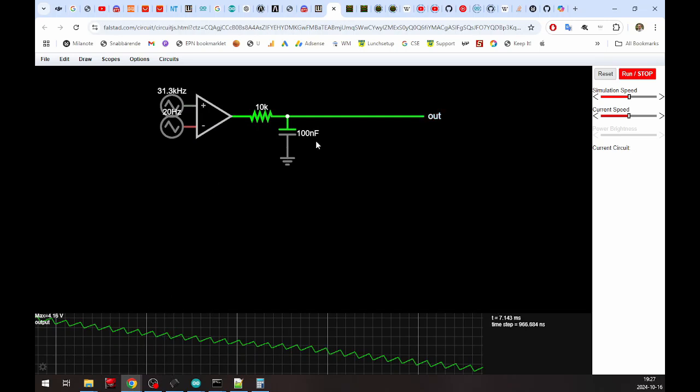So what happens now is that when this output goes to ground, this one capacitor releases the energy it has out on the output, thus smoothing out this surface. And once we get back to 5 volts, it charges the capacitor again. So you get this little triangle square instead of the really huge square wave. And this is what we need.